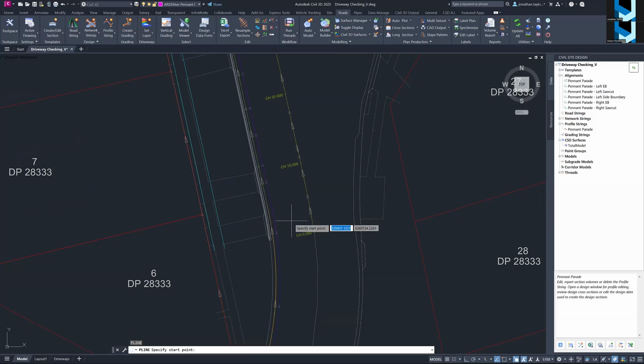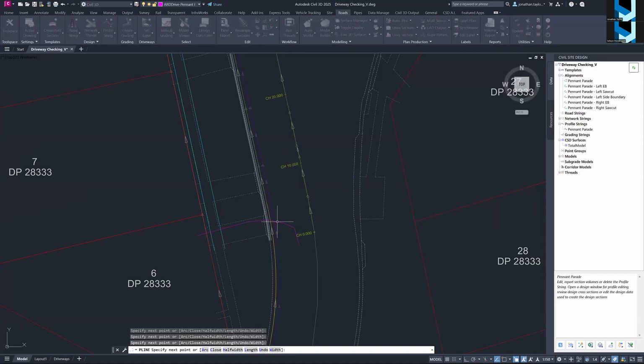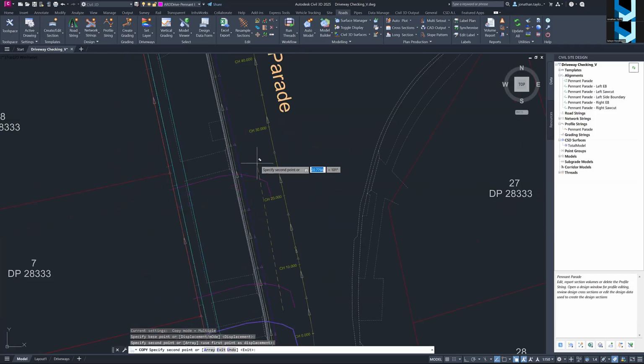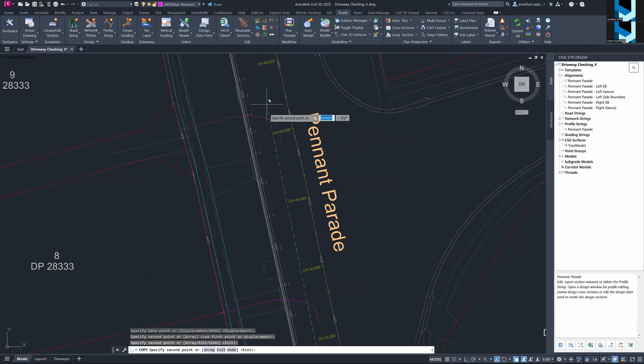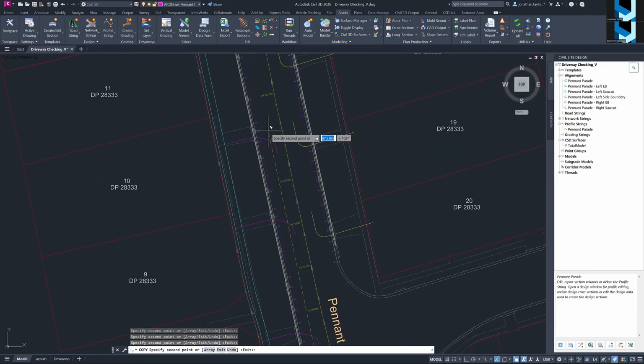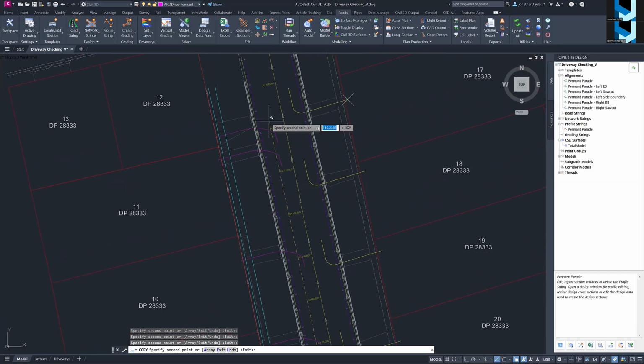In fact, I want to show you what happens if I draw this outside the design, because this end of the polyline won't be in the design, and it will warn me of that. I am going to run this vehicle. Obviously, vehicles don't all enter from this side, I do appreciate that. So what you could do is draw another set of polylines on the same layer with an approach from the opposite side coming in, if you wanted to.